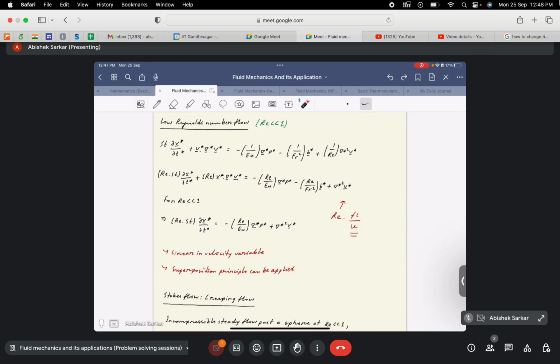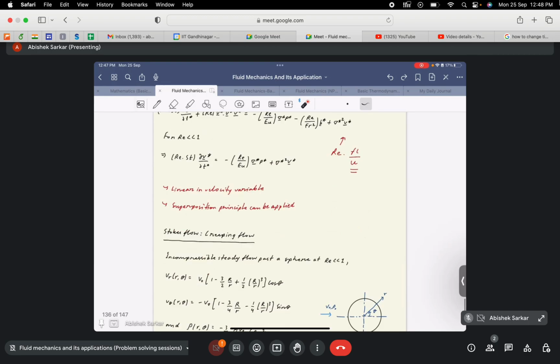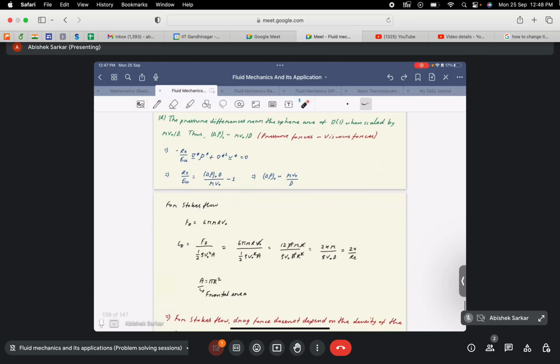Okay, so what this essentially tells us is that in a steady, or creeping, flow regime, the viscous forces are being balanced by the pressure force term. Now, for this pressure force term, this ratio would only be of order 1, because it has no coefficient. So it scales as order 1, and this would remain in the equation if and only if this coefficient scales as order 1. Okay, so if we take this ratio, delta P naught by mu V naught by D, because we have taken the pressure to scale as this, we will get that delta P is mu V naught by D.